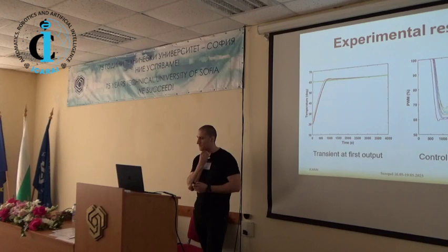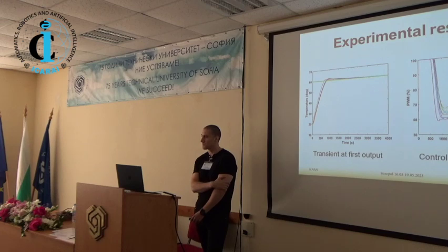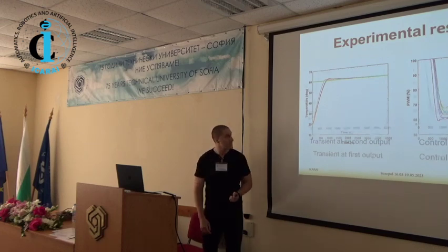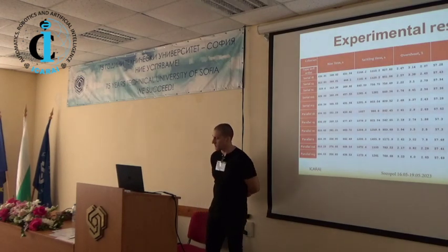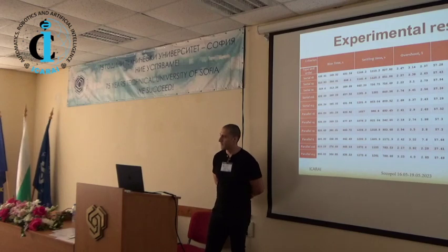Have you made a comparison between these two possibilities? First, reduce the model and design the controller with the reduced order model, and then what you have shown: use the high order model, design a controller, which is also high order since it is H infinity, and then reduce the order.